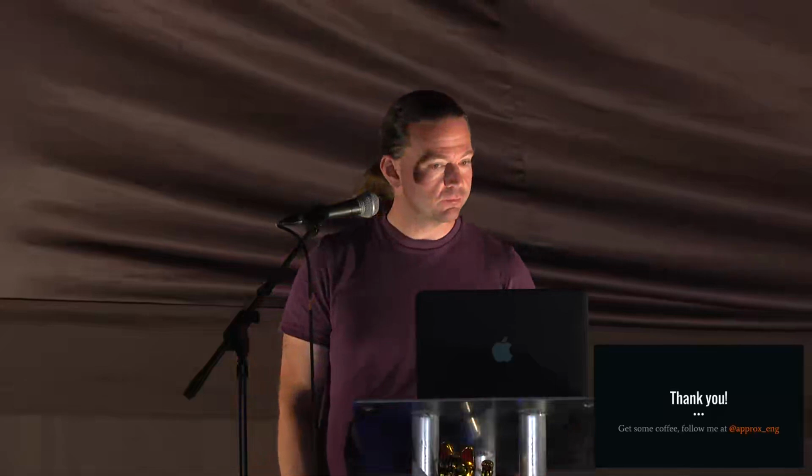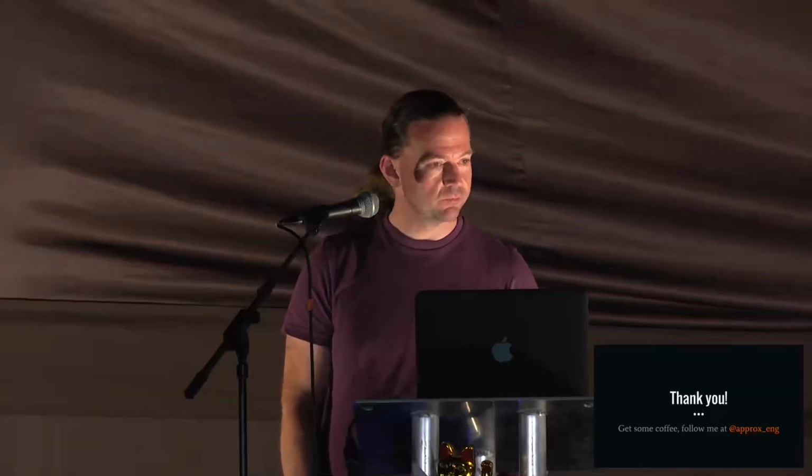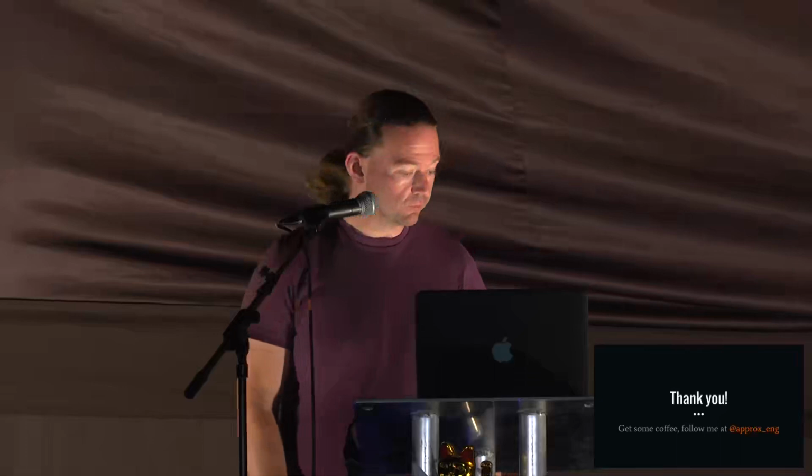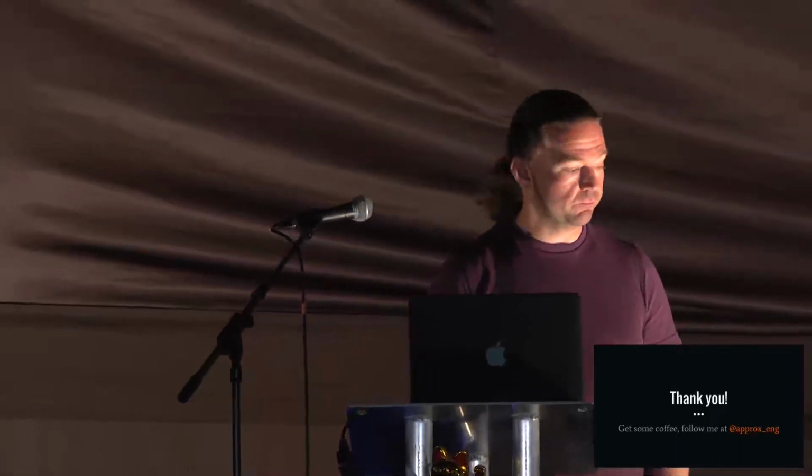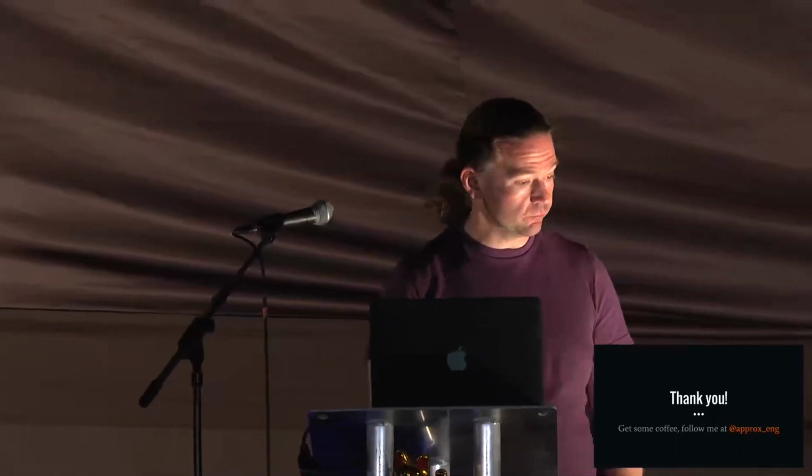Hi. So I'm wondering, a big barrier to people getting involved with this kind of system, this interface, is going to be the hardware, and I'm wondering about what kind of commercial robots this kind of interface would work for. So this actually is used in commercial industrial robots. They don't use omni wheels; they use what are called mecanum wheels. So the omni wheels will drive forwards and slide sideways, if you like. A mecanum wheel will drive diagonally forwards in one direction, slide diagonally in the direction 90 degrees to that.